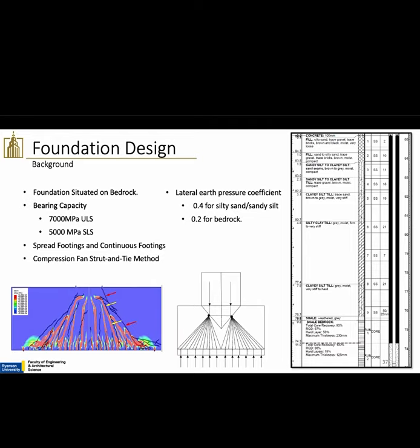Now we have very minimal dimensions in the X and Y direction of the footing. However, we're governed by punching shear, which allowed us to design the deep beam foundation using a compression fan strut and tie method for stress distribution. As well, we have the lateral earth pressure coefficients from the borehole logs as 0.4 for the soil layers above the bedrock and 0.2 for the bedrock.